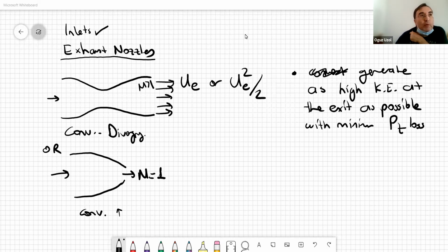Shock waves appear while we are starting the nozzle. If you remember, we discussed things like this. For example, we have a P exit, and we start from subsonic flow. This is the case for rockets, and also for turbo engines. Subsonic flow is incoming. We choke it, M equal to 1, and then we go to supersonic if it's converging-diverging. Then we said, okay, let's start from everywhere subsonic, and then keep reducing PE step by step.